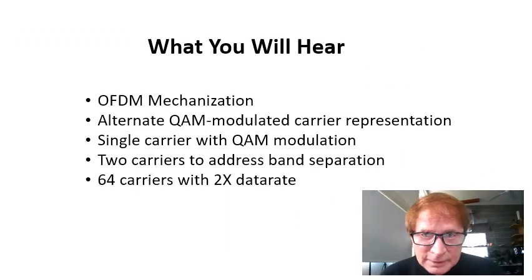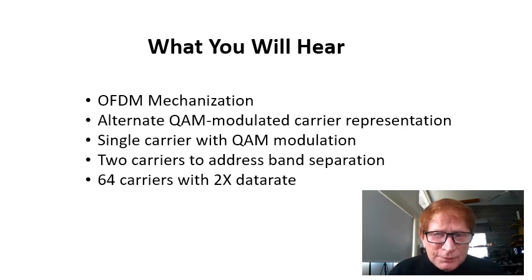We will cover a lot of ground in this material, so let's do a quick summary. We'll first go over the traditional OFDM mechanizations and concepts. Our strategy will be to motivate the new approach by showing that it resolves some constraints that are imposed by the traditional approach. We will introduce a new differential equation representation of an oscillating wave that will allow more flexibility than the more traditional exponential notation representation that is used by the FFT algorithm.